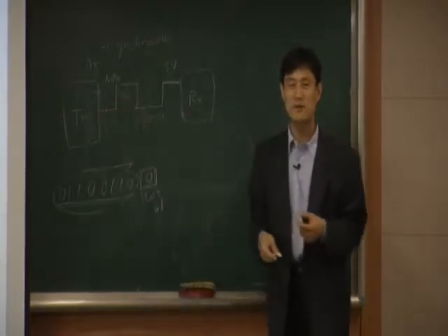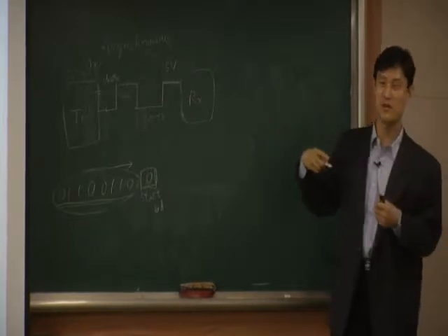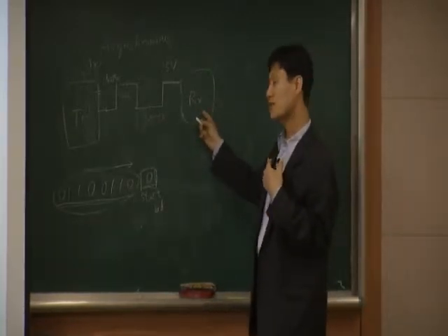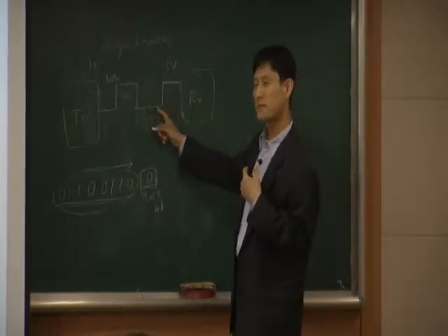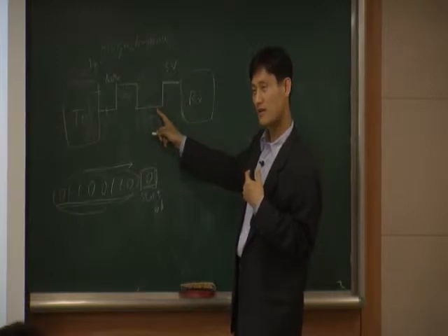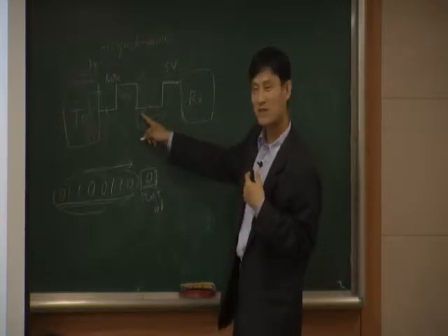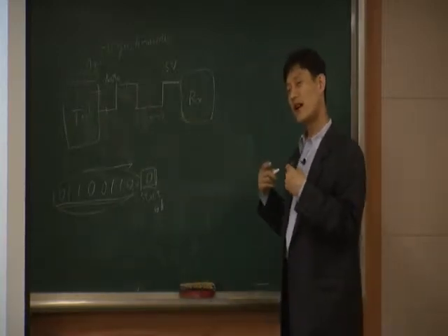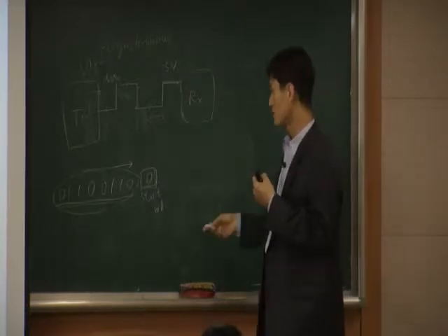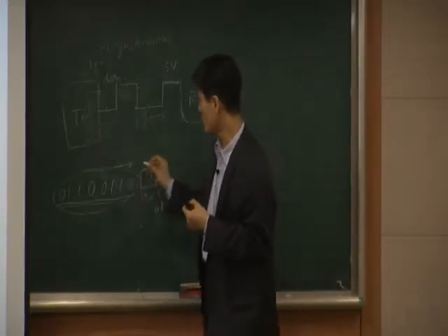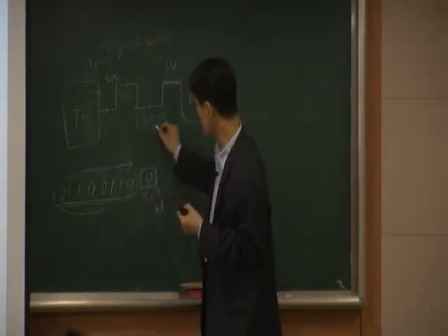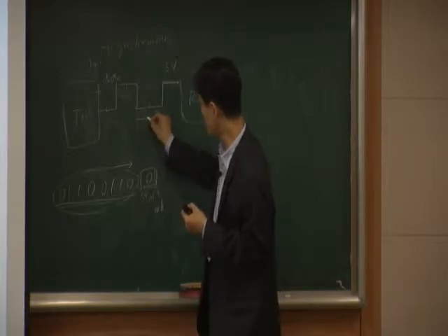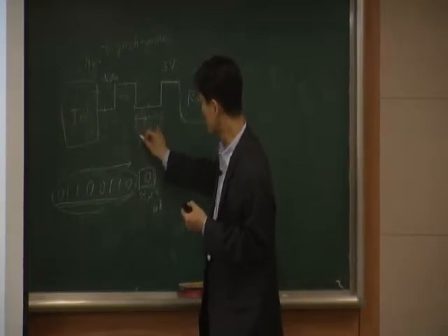So now we have the same problem as before. From the receiver's point of view, it looks like I have a start bit, a 0 here, but we have another 0, right? And we have a 1, 1, 0, 0. So the receiver is now confused because, let's say, initially what the transmitter tries to do is a 1 microsecond bit duration.